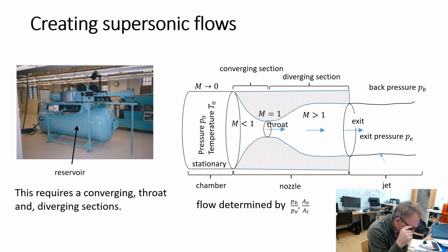And so this is how supersonic flows are actually generated. This is a picture of a laboratory test, standard lab test. And so what we have here is a reservoir of gas. So in the past we used to have one downstairs in the mezzanine floor in the fluids lab, and the tanks, very old, from the 70s, very large. They would have been probably, it must have been two 200 litre steel tanks, ramped up to maybe 50 bar. And so what we do with the reservoir, we charge it up to a high pressure,